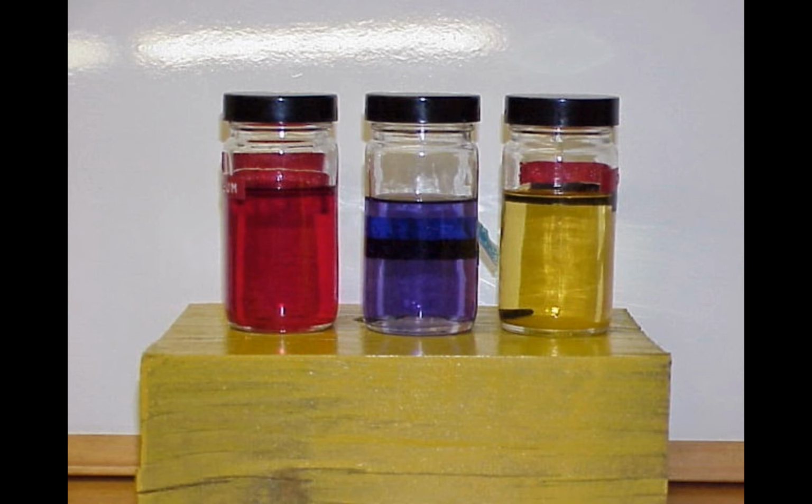How do you determine which type of hydraulic fluid to use in a specific system? Aircraft maintenance manual, plate on reservoir. What will happen to the seals in a vegetable base hydraulic system if it is serviced with mineral base or phosphate ester base fluids? Seals will swell, break down, and block the system.